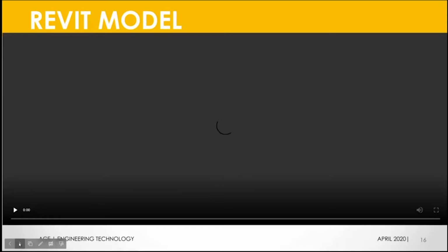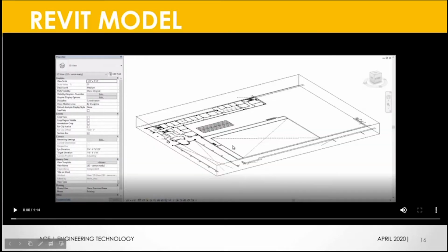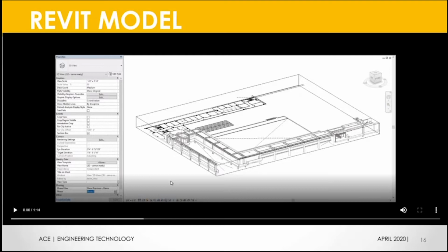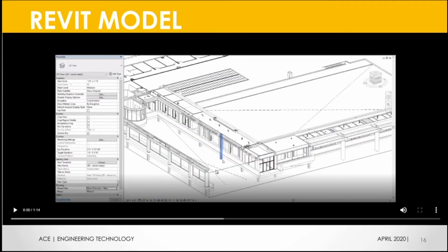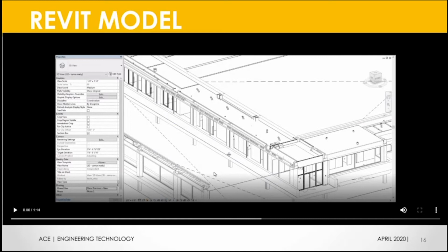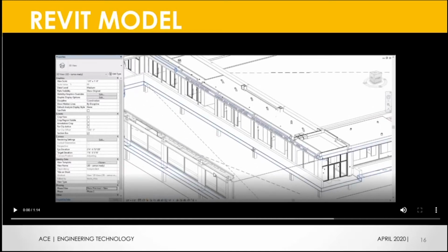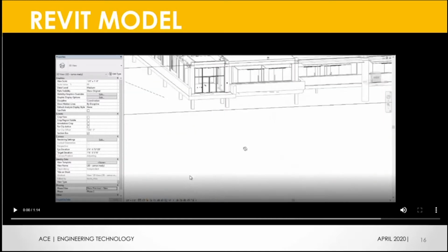In this project, we decided to utilize Revit because the intent was to provide construction documents, not just conceptual drawings. So what we ended up doing, utilizing the scan, and here you see that at the bottom, we are playing with the existing conditions. You can turn on different filters, so you can see this is the existing building, and we start adding the phases of the work so we can phase what we are trying to present to the client. It gives them a better understanding of what they have, what they expect of the final product, and build the project in the virtual world before it goes to construction.